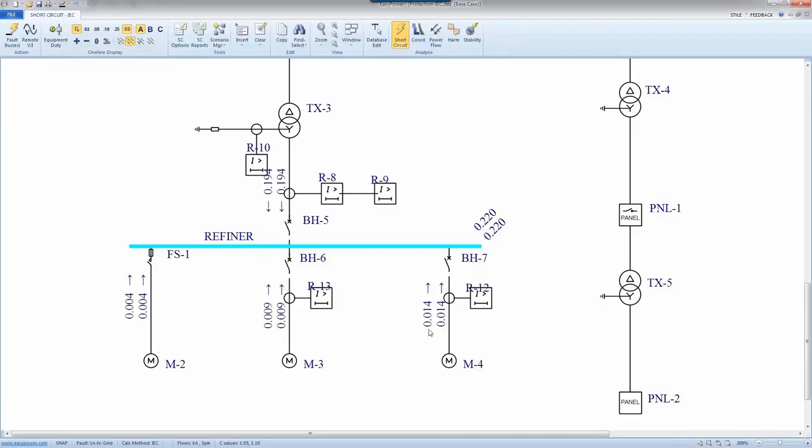IEC recommends that you do not change the initial and do not change the braking, keep them as they are. As you would see for unbalanced faults, it doesn't even show a decay. That's the IEC recommendation, and the steady state is not cut off, it's there. So that statement, one more time, has an exception.